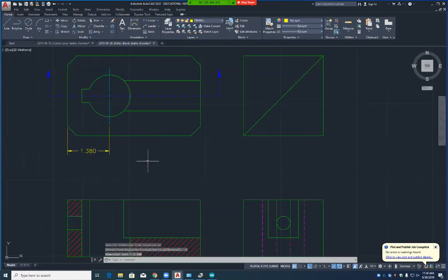Exactly. Huge point. A lot of students have a really hard time. It's a 1/2 inch off your cutting plane line when you work with the cutting plane line. So we have to be a 1/2 inch from here out, not from our object.